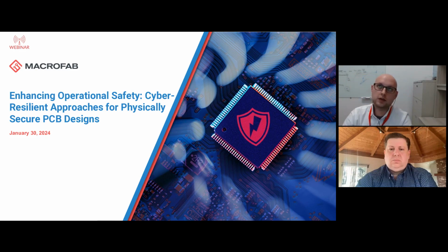You'll see a lot of this happens with, like I mentioned before, there was an attack on a hardware Bitcoin wallet. One of the things they were doing is basically trying to glitch the chip by making it operate outside of its intended power supply standards. And so again, trying to detect that. As soon as the power supply in your design is outside of the range it should be operating in, it is probably a good sign that you may want to try and secure your data.